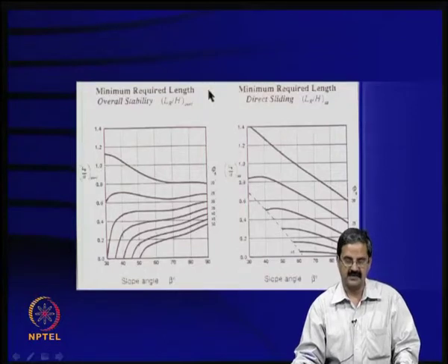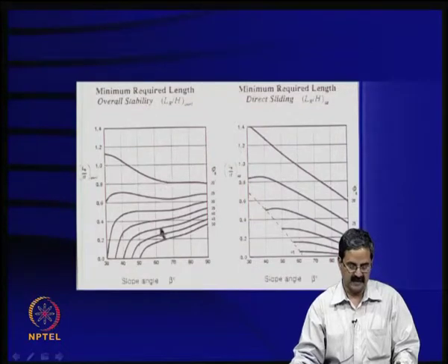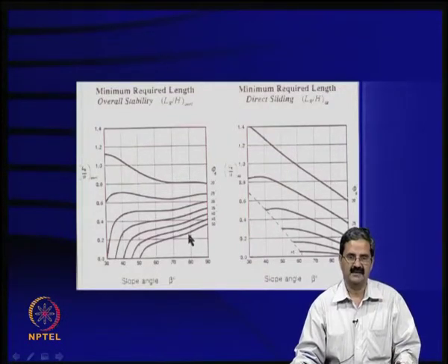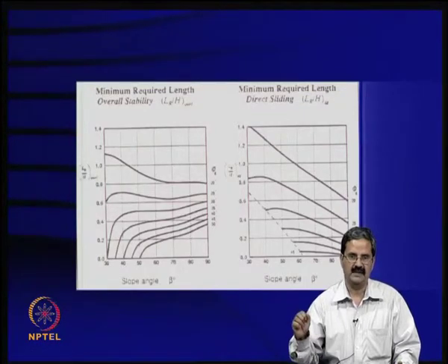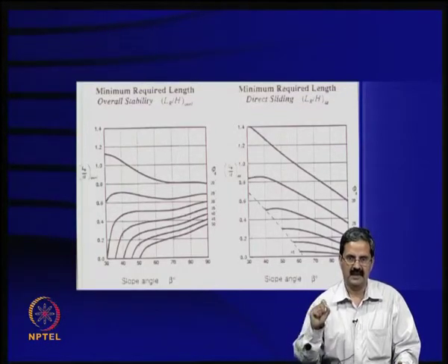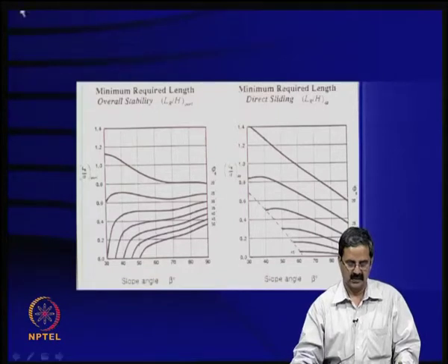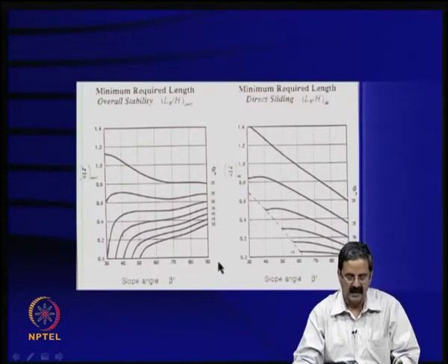And as I just mentioned, we try to calculate the required force, and also what is the length now. It is very important to understand that, as I mentioned in the previous class, if the height is say 10 meters, 0.7 times will be the length of the reinforcement. So, that is about vertical, and that is just a preliminary guideline.